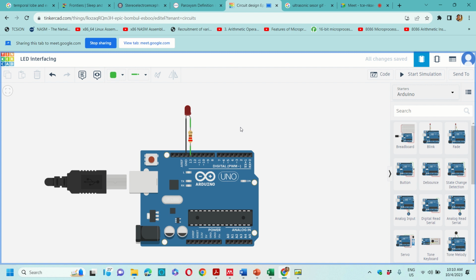We call them common cathode or common anode, but instead of that, you can even say how the LED can be used. I can use an LED by providing my digital signal to the anode or to the cathode. If I am providing a digital signal to the anode, then the cathode should be connected to ground or VCC.